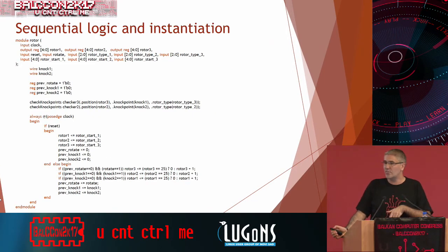Everything else can be checked inside that clock cycle. So you have here a reset, and we will reset only on a positive edge, basically on each clock. So we will not have situations when the reset is fluctuating, so that we keep resetting the device, and then we will not be able to follow up.